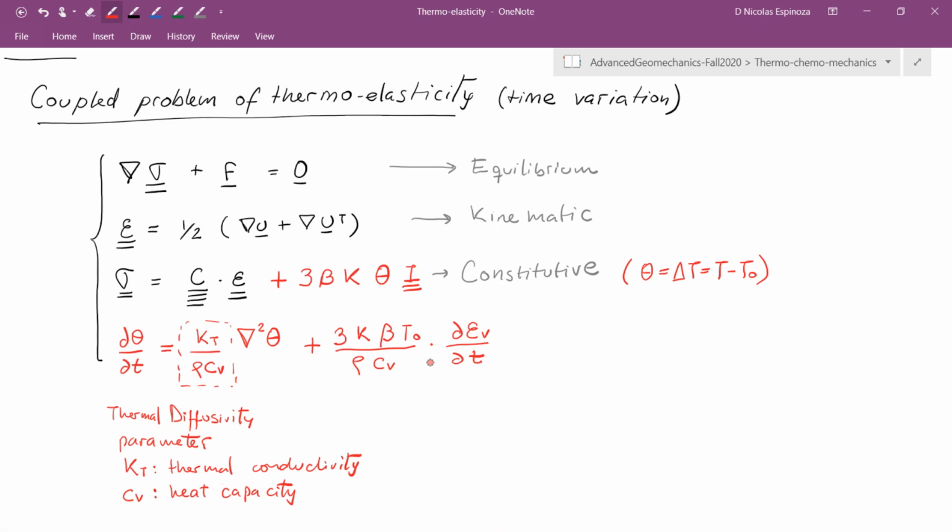So instead, what you can do is you can bend it back and forth. And that bending back and forth is going to heat up the wire and is going to lower its tensile strength. The heating is this component. It is the variation of strain that causes an increase of temperature that lowers the tensile strength of the material and makes it possible to just cut a piece of steel wire just with your bare hands. So if you've never tried that, please do that.